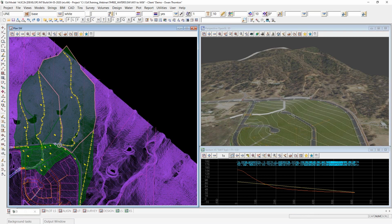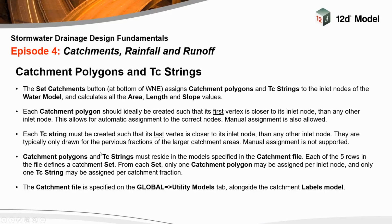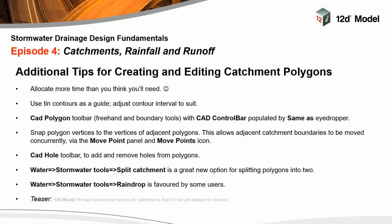The last little slide then, and I know I sort of glossed over the whole how do you draw polygons inside 12D. Again, there's lots of different ways to draw polygons, but there's nothing fantastic in 12D at this stage, at least, for actually drawing catchment polygons. Lots of great tools for drawing polygons, but if you need to sit down and create a whole lot of catchment polygons, my tip would be first up to allocate more time than you think you'll need, because there's no getting away from the fact that at the moment it is a very time-consuming process, and it is possibly the biggest bottleneck in the whole stormwater design process.